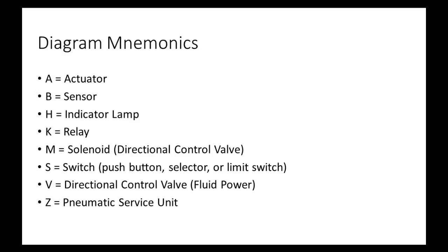Relay contact. Yeah, but it's an electromechanical device, right? We control it with electricity, but it's a mechanical device, so its contacts are mechanical. Our PLC is going to do away with relays, never. The PLCs don't put out enough drive. If they did, they would be huge. Now they're little tiny boxes, so they don't put out enough current drive to run a sure enough motor. So what that means is that we use the PLC to pick up what we call a contactor, and then the contactor can run these big high power loads.